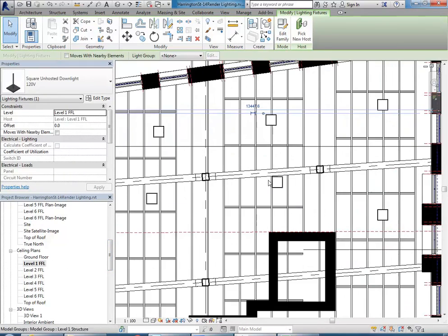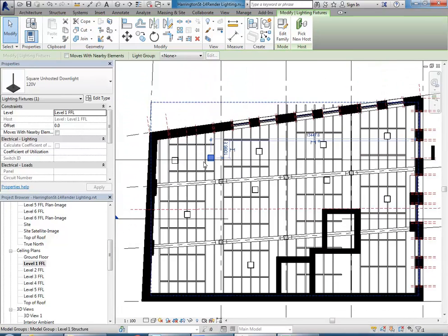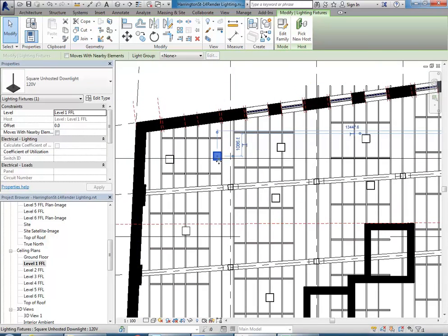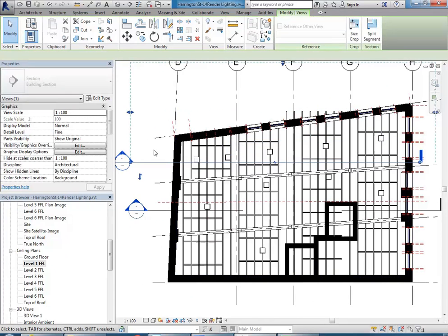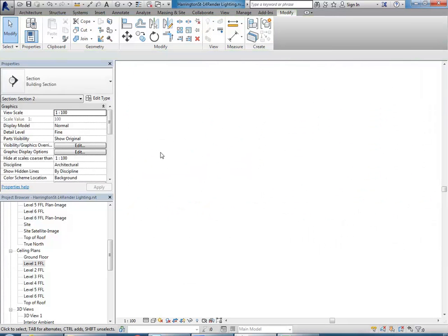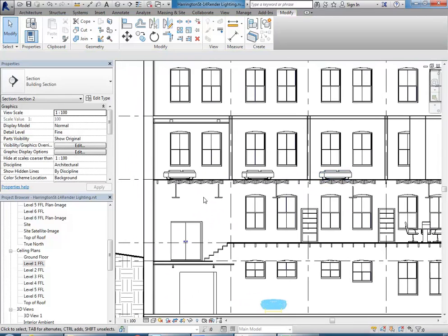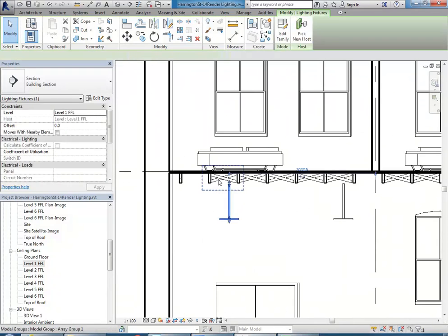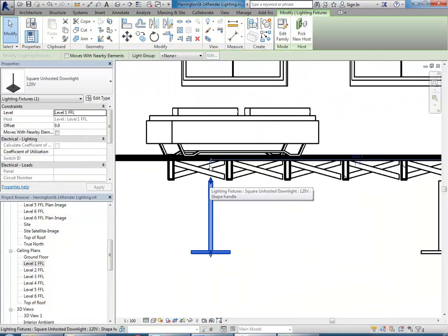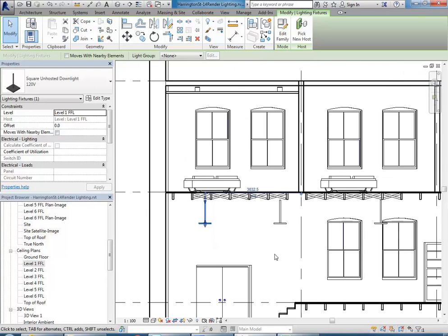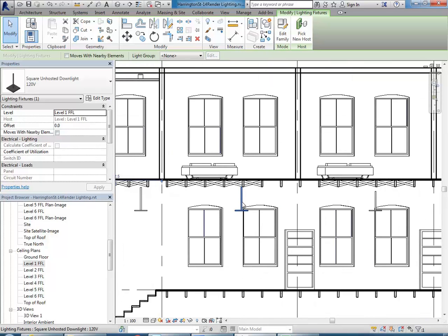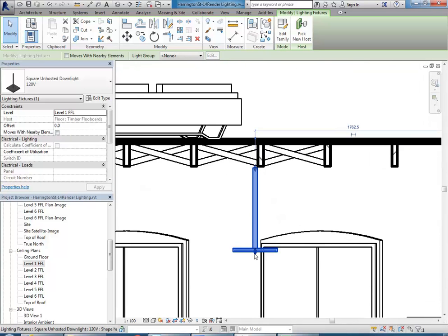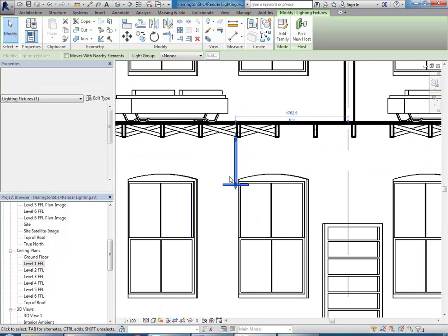So now I can maybe go into here and change the views, but unfortunately the height to the ceiling is an instance property, and we need it to be like that so that I can stretch each one. But I'll show you a quick way of doing that to all of them. So firstly, I'm going to get the height from the ground right. Now you can try stretching it, but that's a little bit hit and miss.